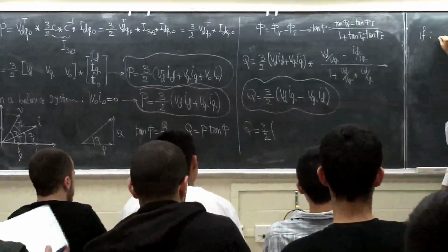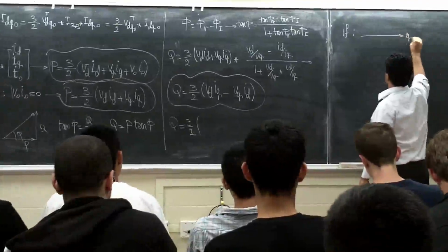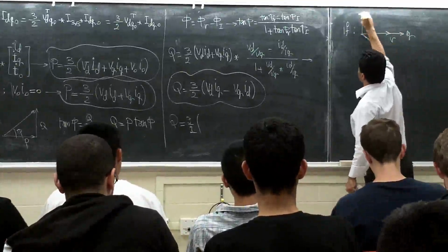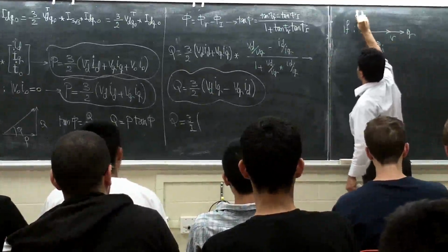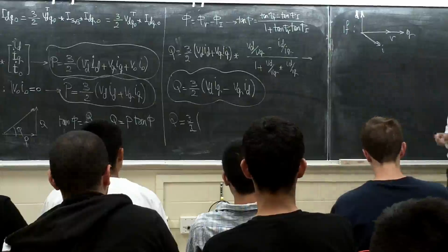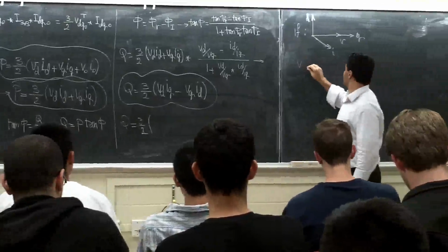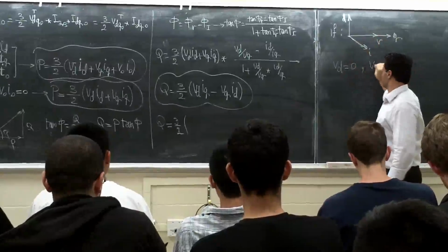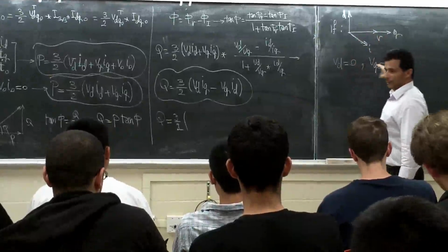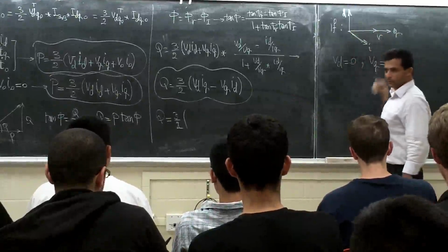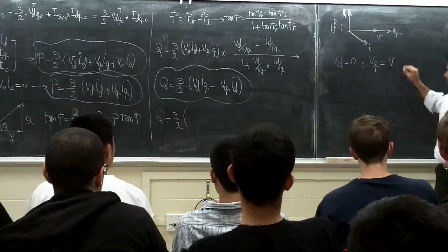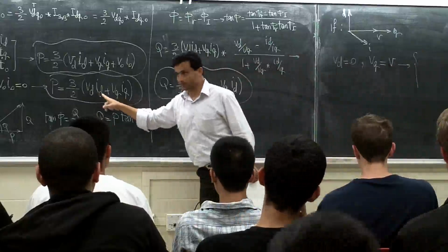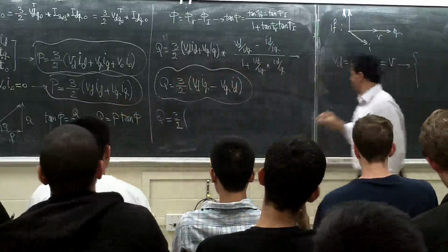If I select the Q axis like this, this is the Q, this is the V, this is the I, and this is the D. What is going to happen? How much is the Vd? How much is the Vq? Whatever V is here, Vq is going to be that much. So what is going to result here? Just replace them here. Vd is 0.